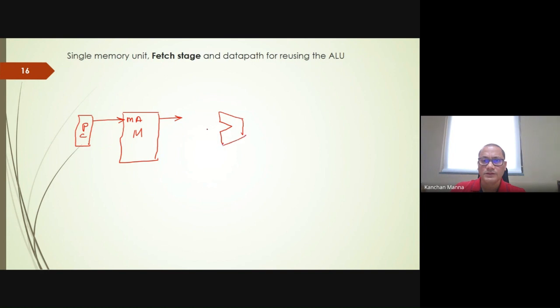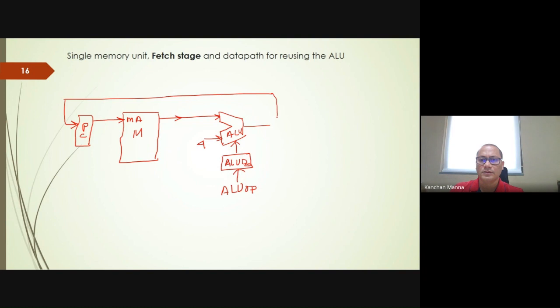So this is the ALU, and we'll provide 4 here. And if you remember, the ALU has an ALU decoder. So this is our ALU decoder. We have to provide the ALU op field input, and the controller will provide this ALU op. Then it will perform the addition, and then we load that result into the PC. Got it?